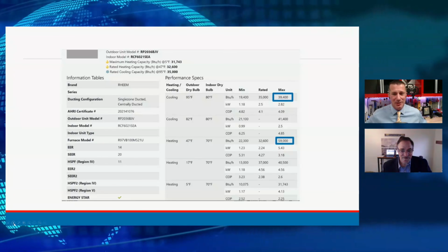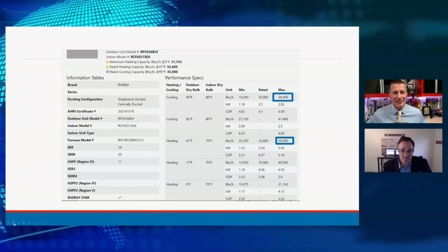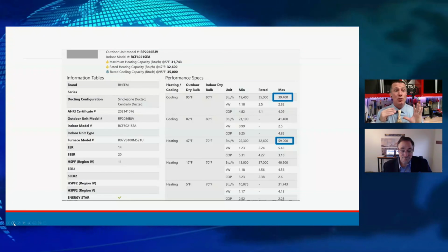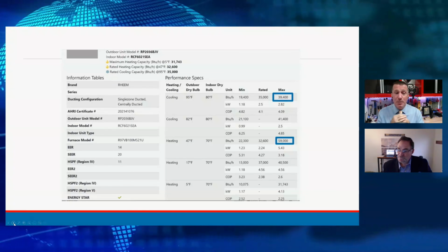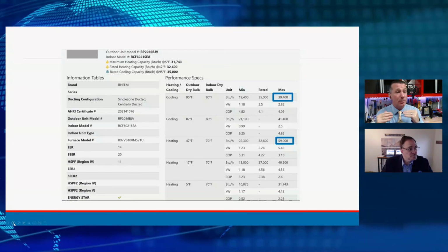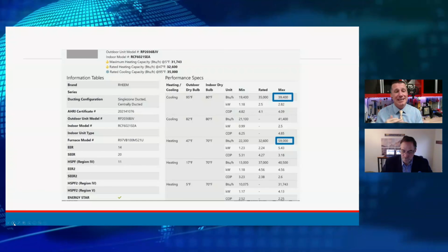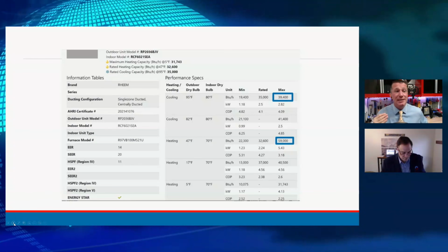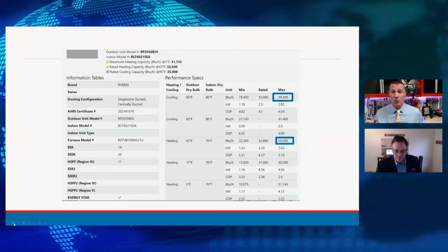This is the point where a lot of people get stuck, on how to interpret what's going on here. So remember when we were talking about our inverter, when we move into our fully variable speed compressor, and we have the ability to ramp that compressor, especially if it's a rotary that's going from 1,000 all the way up to 7,000 RPMs. Can't I modulate everywhere in between? Can I over-ramp that compressor? That's exactly what we're doing.